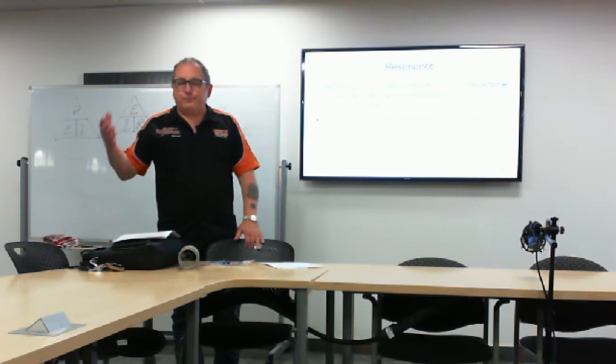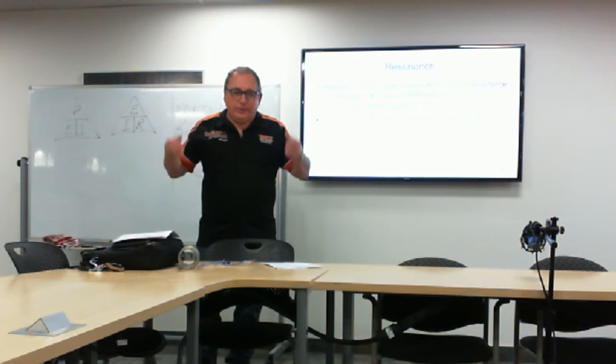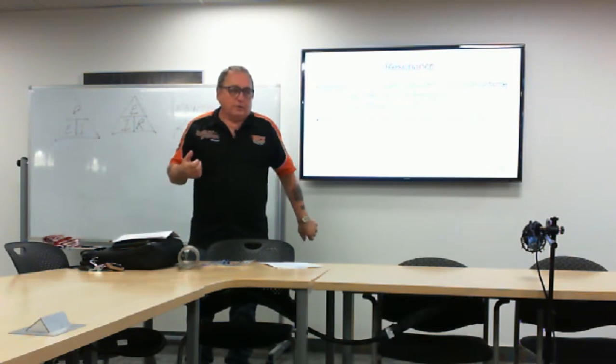Nowadays, it's all done by a little bit different technology. It's done by electronics, and we don't use that except in antenna tuners and high current amplifiers. And the big amplifiers, you need a big tuner for them, because remember, this is where impedance comes in, because you have to impedance match your antenna to your radio or to your output. So the impedances have to be the same so that they can pass the maximum amount of current. If they're not the same, then you have losses, and that's where you get damage.